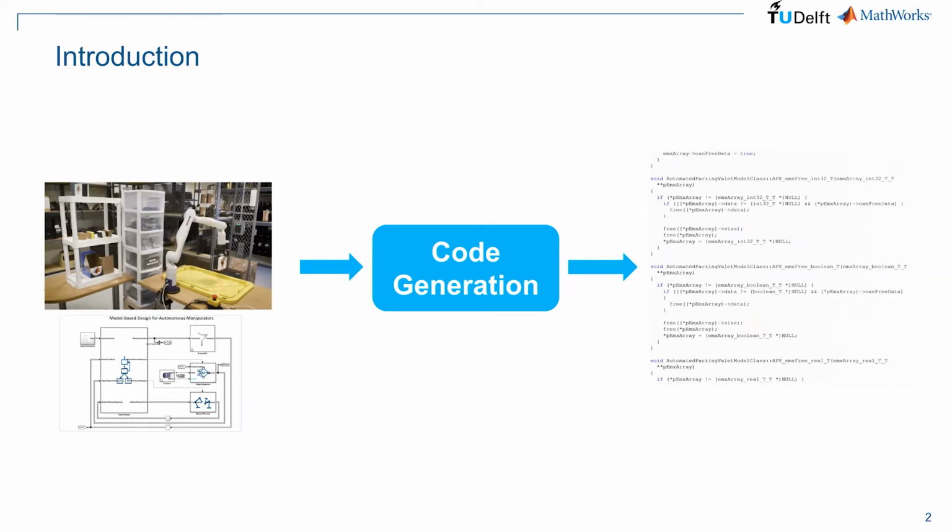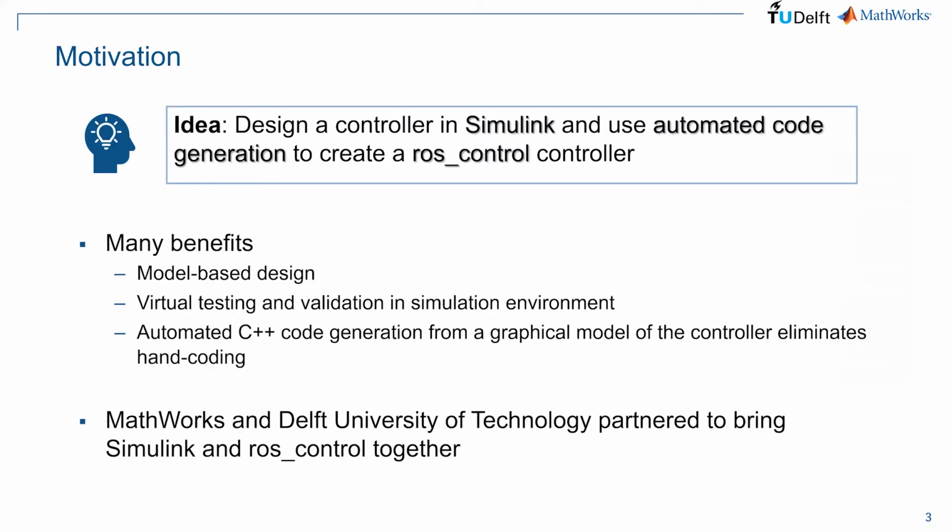And then you can also simulate the plant and finally simulate the controller together with it using model-driven or model-in-the-loop simulation, for instance. And at the end, you can actually use code generation to take whatever you designed in Simulink and generate it out into various programming languages such as C, C++, but also HDL, for instance, and many others. And the main reason you want to do this is because it just reduces hand coding a lot and reduces your time to market.